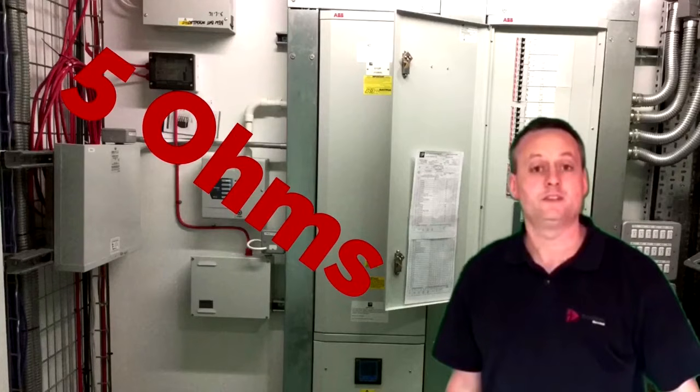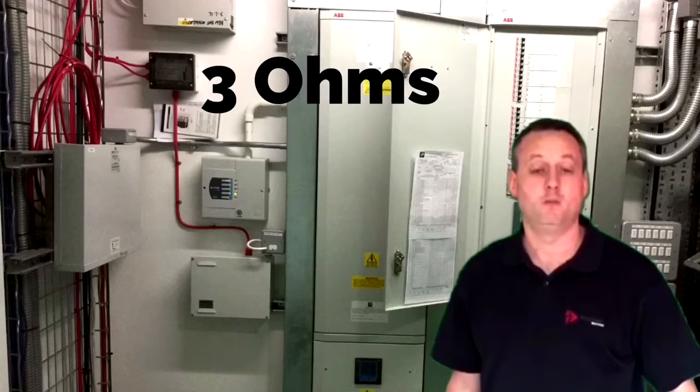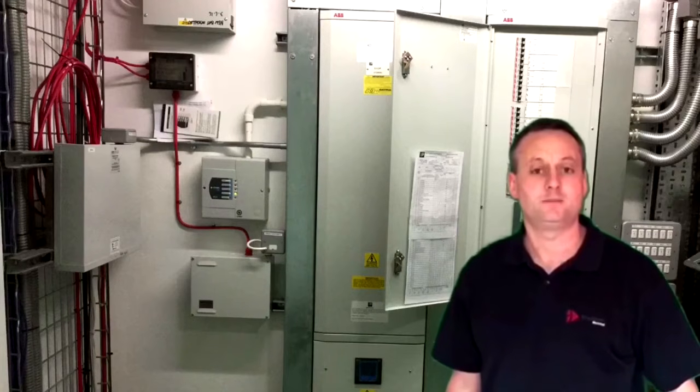If we have 3 resistors connected in parallel, all of say 9 ohms each, the total resistance in that circuit would be 3 ohms. In other words, a third of one of the resistors. And we can see how this pattern moves on as we go to 4, etc.